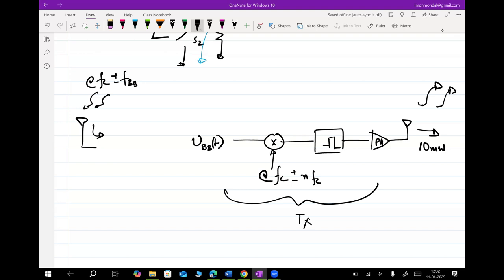And typically these losses are humongous, so much so that you cannot express them in linear scale. What you can typically receive is of the order of less than 1 nanowatt, a few picowatts, tens of picowatts. That is the strength of the signal that you receive. As you can see, going from milli to pico and nano is a mess.